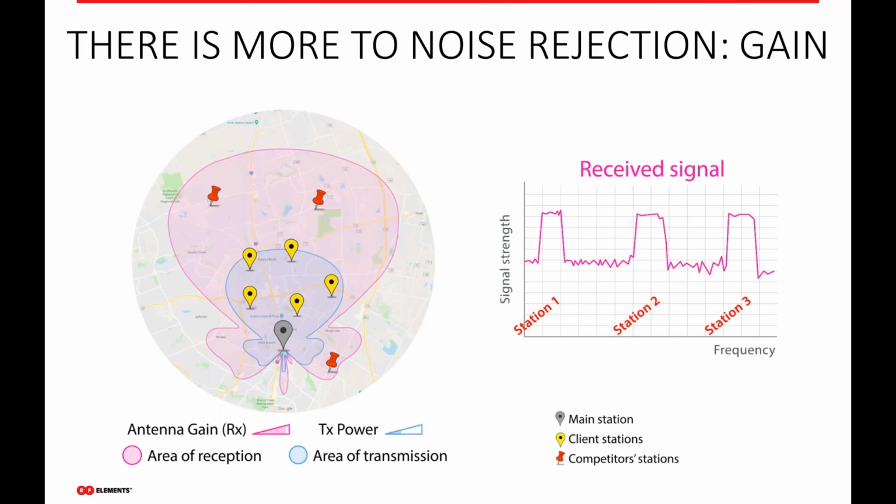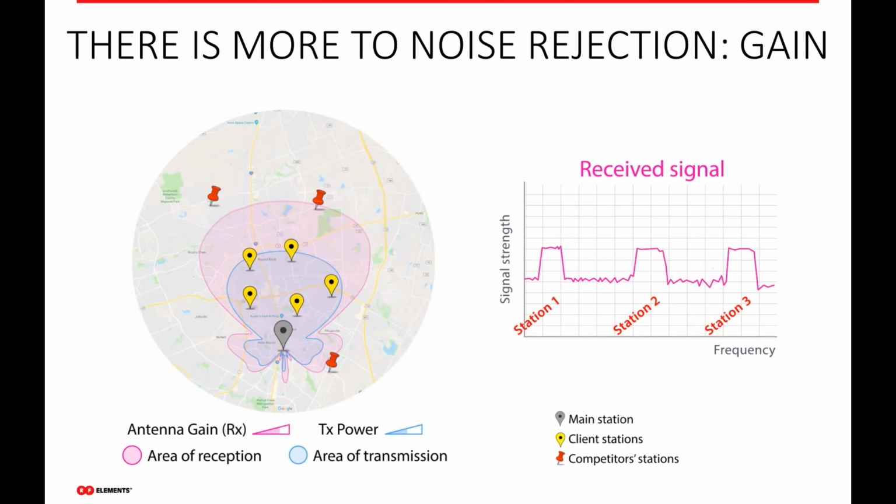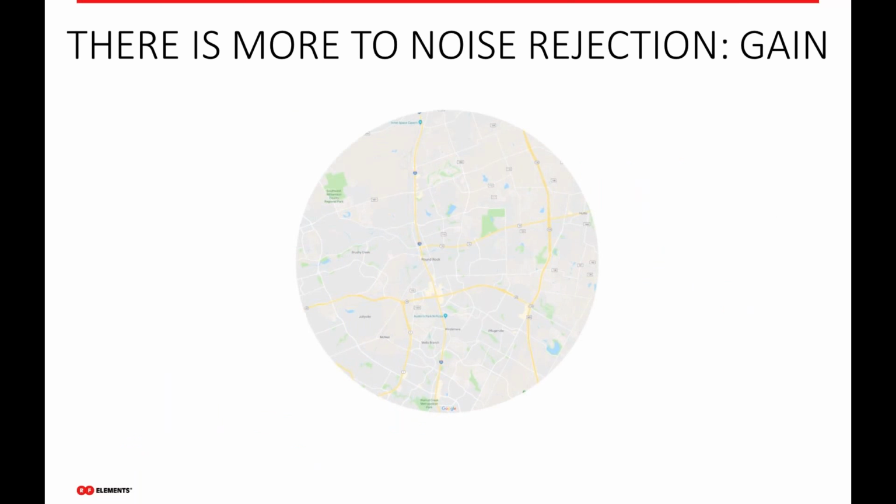Again, using appropriate down tilt for higher gain horns, or using lower gain overall, depending on your density and how you have to build out your network. You really get that granularity with horns that you don't get with traditional sectors.